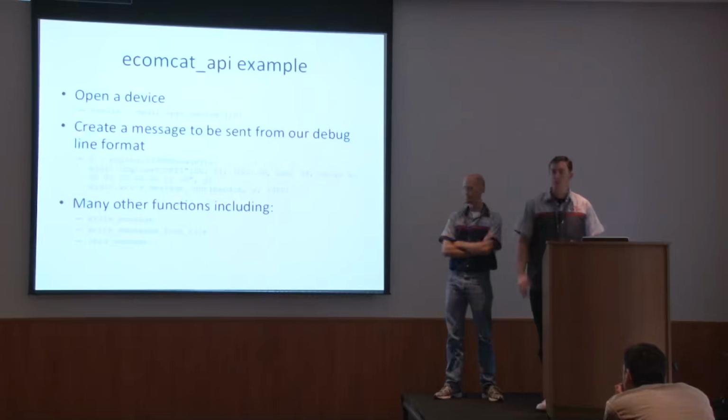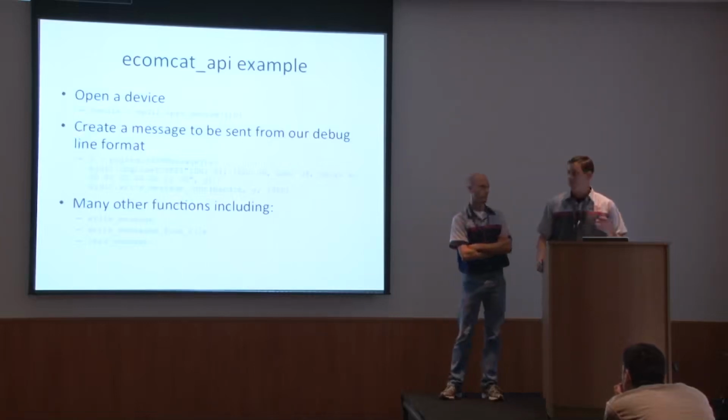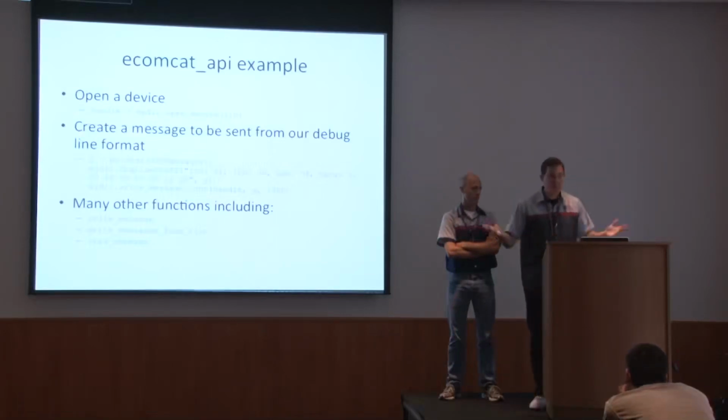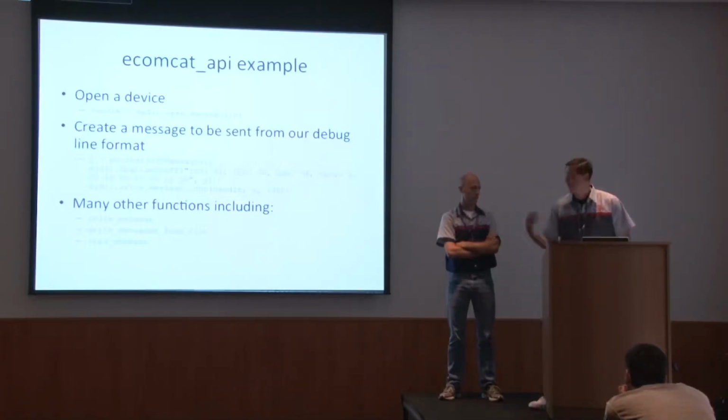This was one of our goals. We wanted to bring this research to more people, so you didn't have to spend the time figuring all this stuff out. You can download our library, start sending messages to your car or reading messages quite easily. We have other functions such as writing messages, write a message from a file, so you can actually take a dump like you would in Wireshark to a file and then input that file to try to recreate a scenario in the car.